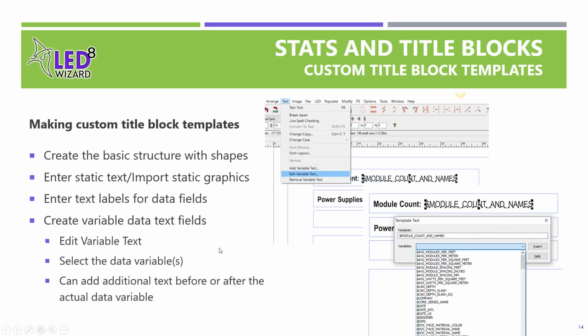So, first thing I would do in the title block, create the basic structure with some shapes, put in some static text, import some static graphics. Again, if you're starting from scratch, we'll create some text labels, right? So here, power supplies, module count, basic labels, and then we'll create the variable data text fields. These are the text fields like here, $ module count and names. And you get to that in this edit variable text option in the text menu.